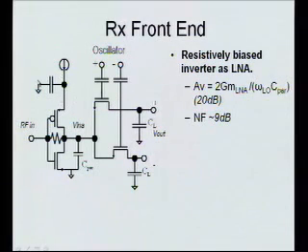The reason you care about this is this bias current is coming from your oscillator. So if this bias current changed dramatically based on random things in your LNA, that'd mean your frequency would shift because you'd be pulling your oscillator around, and it'd be a disaster. So you really want some good isolation there. That was the motivation. Now my mixer, yes, those are exactly two FETs, and they're switches. So basically, when the oscillator's cocked one way, this guy turns on, this guy turns off, and the output is connected to the input. Let's flip the other way, it's the other way. That's it.